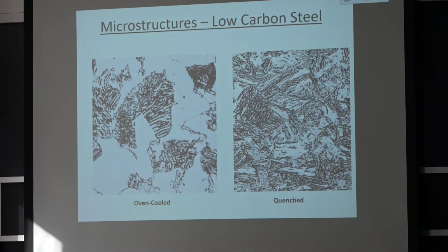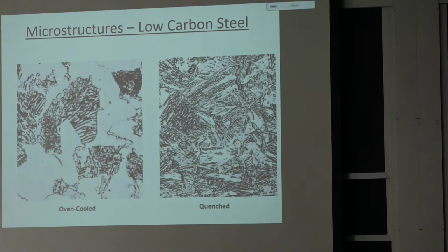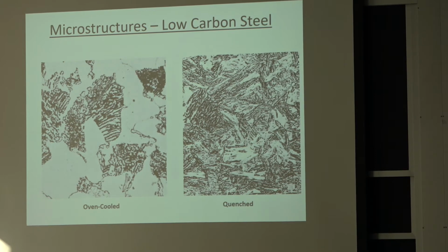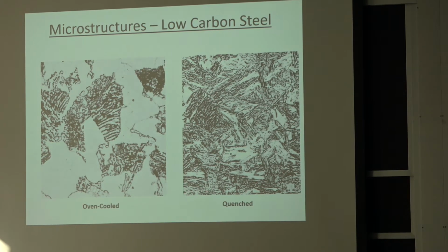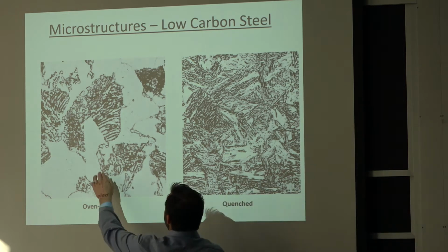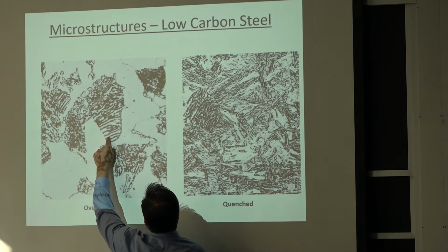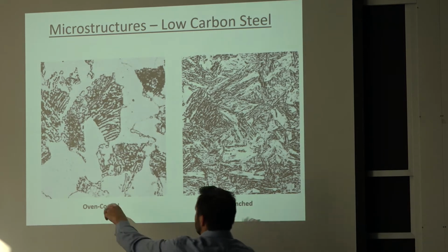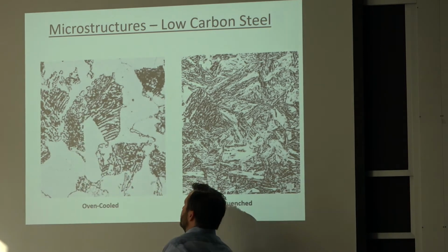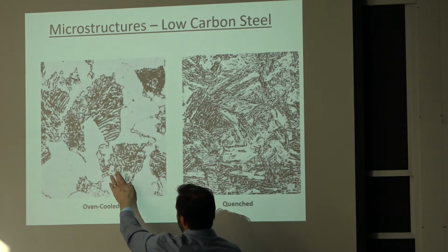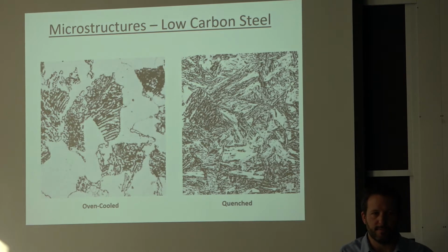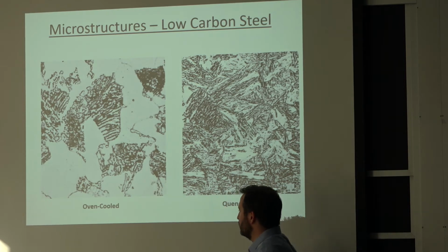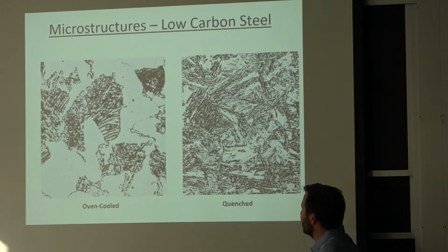So for steel, that was a slightly different story. I said that you have this diffusionless transformation when you cool it off. And when you have diffusion, those lamellar structures, I don't think I had a good image of it yesterday, but here you can see the dark zones that are carbon-rich, and the white zones are the grains that are just the iron, and that's typical for low-carbon steel. And then you have other grains that have a mixture of the very hard and the soft phase. So that is the type of microstructure that gives you the 30 KSI or 200 megapascal yield strength.